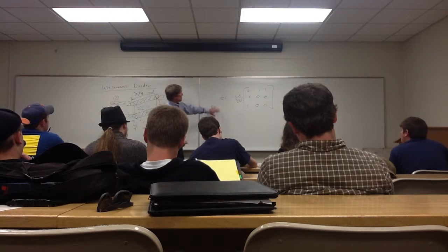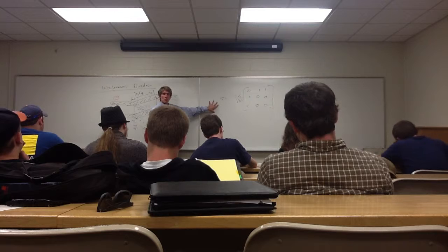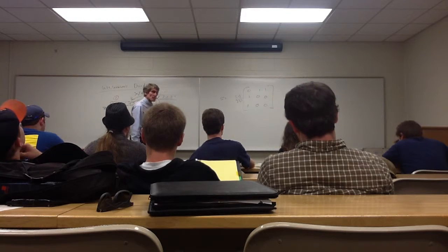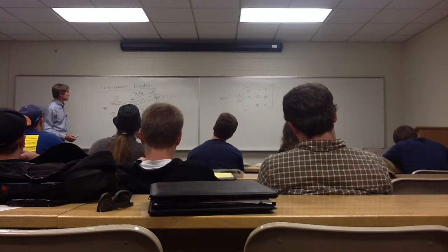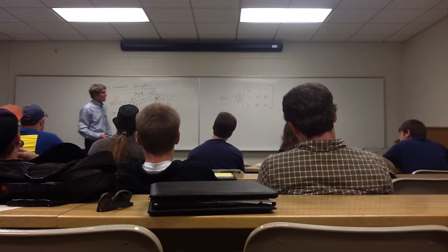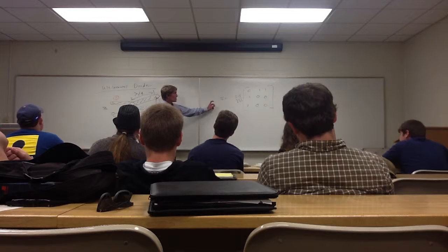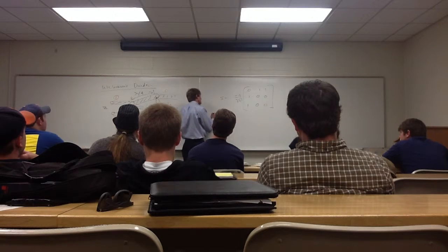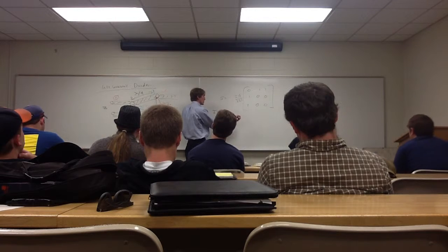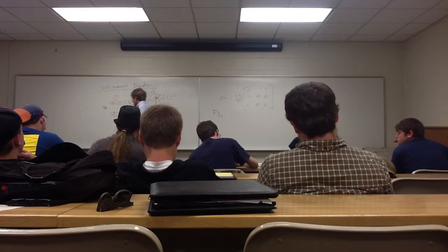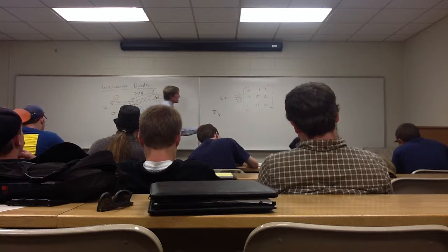Now the reason I'm going to mention the Wilkinson divider, we're going to see something on this, and this is the important thing. You can look at this drawing up in the book. For a Wilkinson divider, with those being the S parameters, look at the insertion loss on the 2-1 term, in other words, the insertion loss for this term right here.